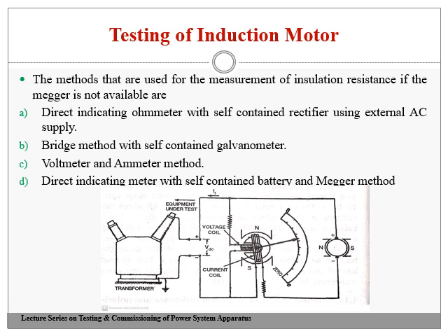That's why we say the current coil produces a deflecting torque in a clockwise direction. When it is shorted, the current in the current coil is maximum and that in the potential coil is minimum. Hence the torque moves the needle to the right side, and it shows zero.